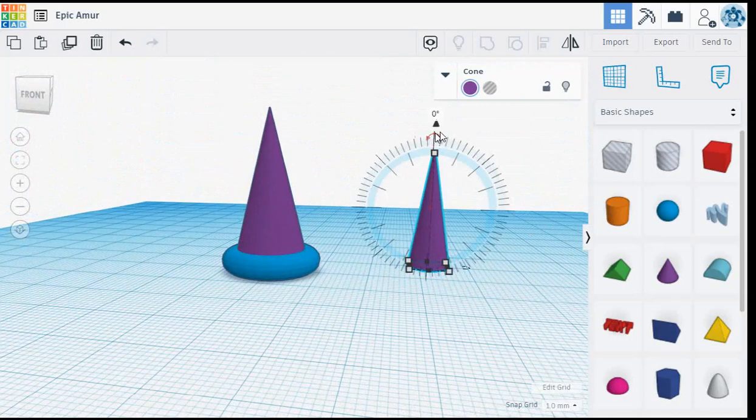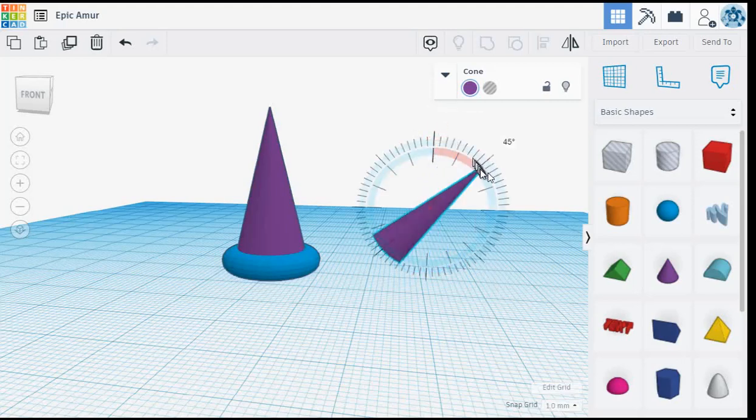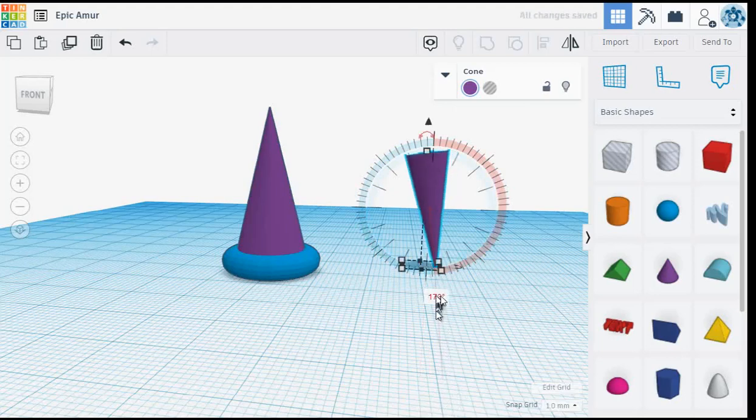By clicking anywhere in the region of this little red arrow, I can change the orientation to be at any angle that moves by, oh, I forget if it's 1 degree or 15 degrees. I want to make it 180. So sometimes it's hard to get 180. If you move your mouse down lower, you have much more control to get it to be 180. Or you can just let go before you do anything else, click inside that and type 180, and press enter. And now it is.